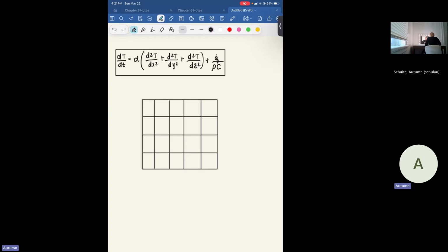Now I want to take our heat diffusion equation that we just derived using Cartesian coordinates, and this time I want to model it using finite differencing, but only in 2D with no energy generation and at steady state. So to simplify our equation, for now I am going to keep our derivative of temperature with time in, just for now.